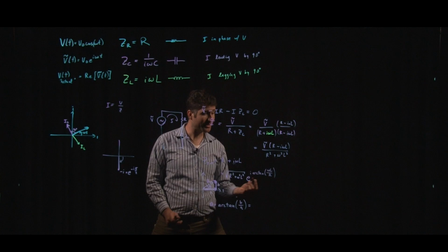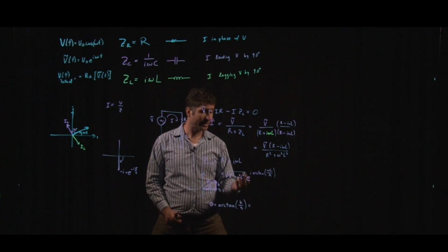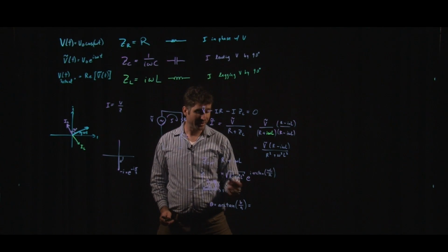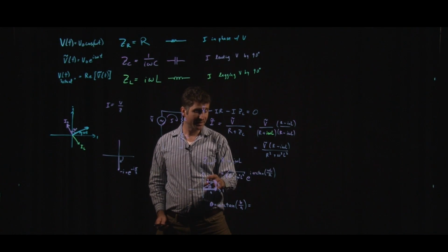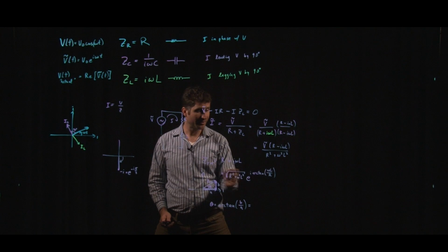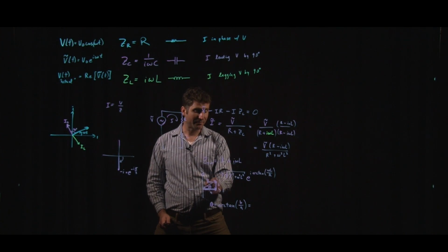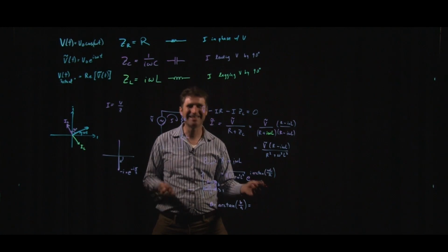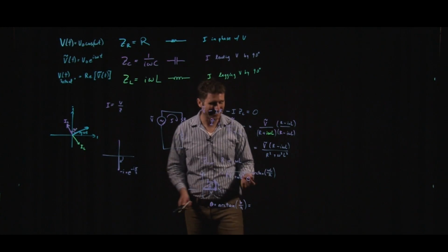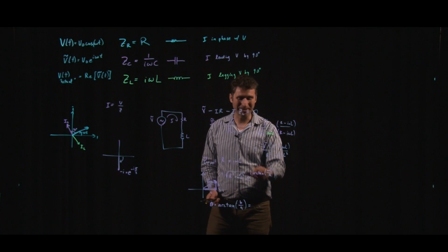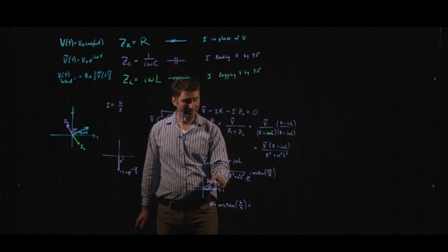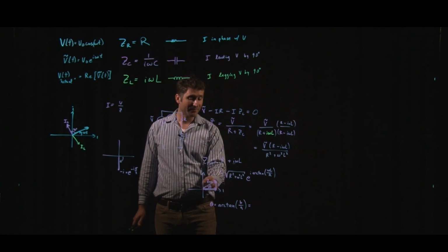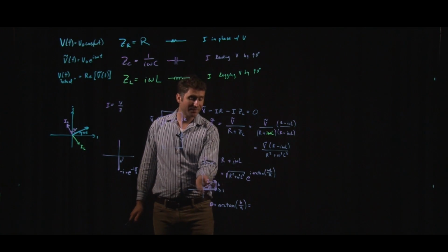So this is actually kind of helpful because this will tell me what the actual phase lead or lag is. And so I can actually read off this angle here visually, right? Of course, I know that taking an arctangent, we need to use maybe some calculator to actually compute this, but nonetheless, that's how we do it. But look, you can actually visually read this off, that if omega L is this much and R is this much, then this is your Z with this phase here.